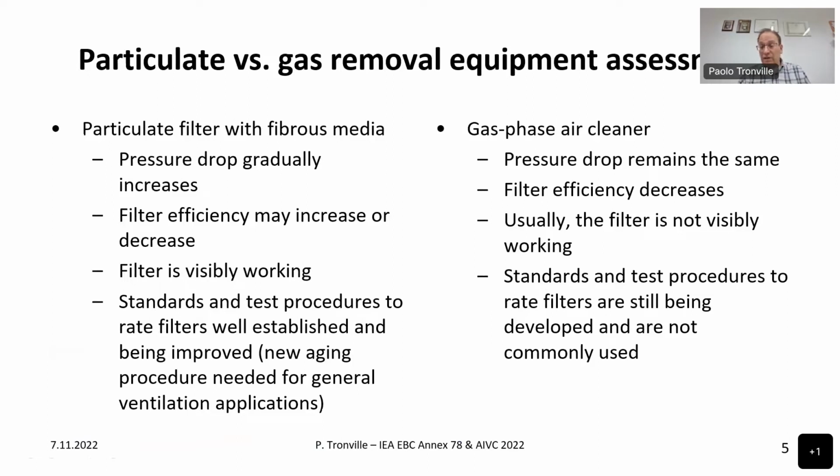So it's also critical to understand when the filter is not operating anymore and therefore should be replaced or maintained in some way. The filter is visibly working in the case of particle filters, so we can see the particles that are captured on the surface of the filter material, while in the case of gas phase filters, except for some cases in which we can see the color of the pellets change, we cannot establish whether the filter is actually working or not.